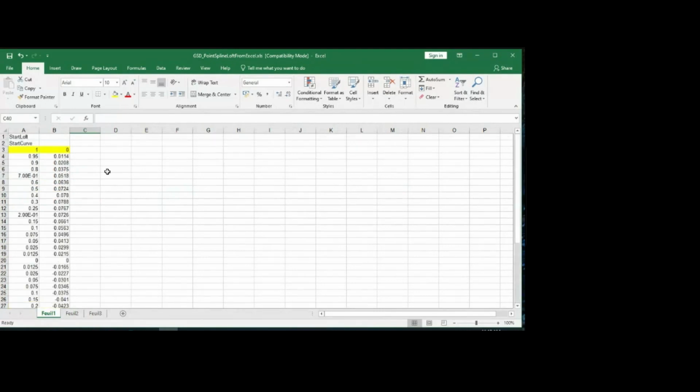But this Catia software is mainly for 3D design. Whether you are importing 3D design or 2D design, we have to give all three coordinates. If you try to import with two coordinates, the software will show an error. So it needs three coordinates, but as it is a 2D profile, the third coordinate will simply be 0.